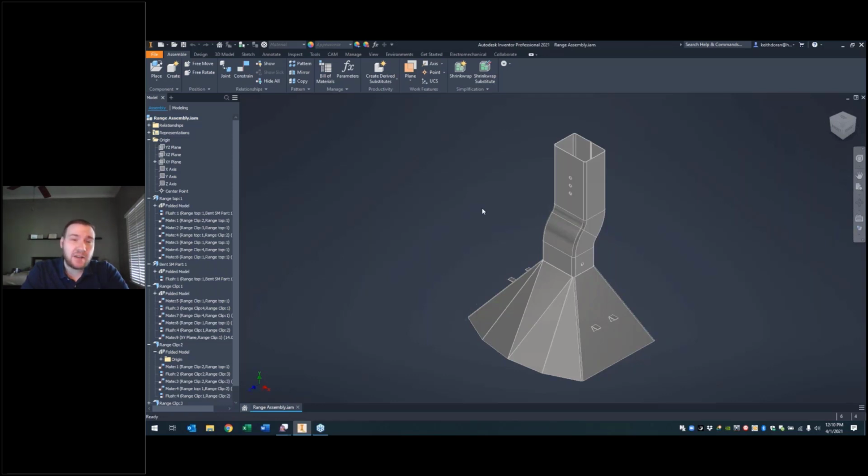Now, with that being said, the first big aspect is if I'm working with sheet metal, it's got to be flattenable. If it's a component that doesn't flatten properly, it's not going to work in the nesting tool. That being said, things like your standard stamping functionality that creates non-uniform shapes are fine. But if you imported a sheet metal component with non-uniform thickness and it doesn't flatten, it's not going to work. Similarly, if I were to work with a standard component, say a woodworking component, I can take that standard component and add a couple of additional steps to it, and the nesting tool will understand that.